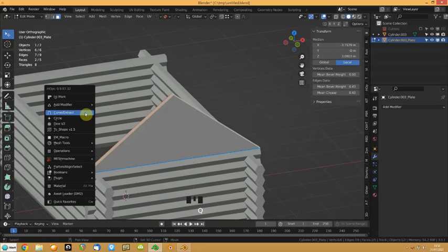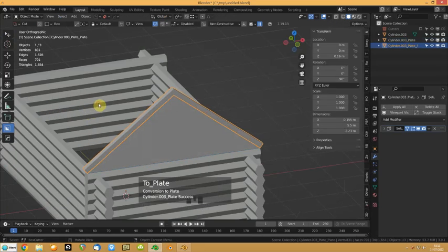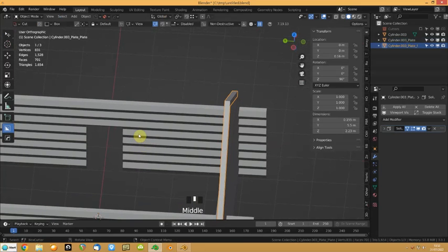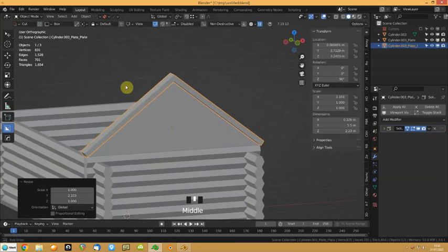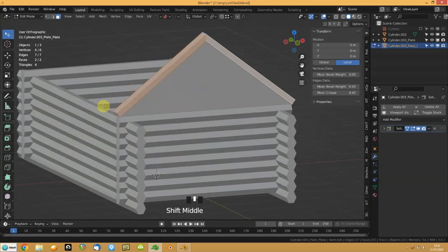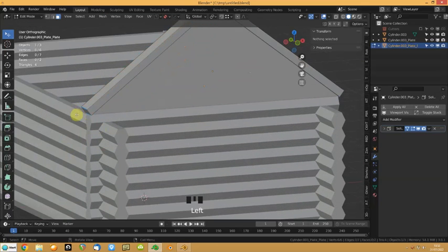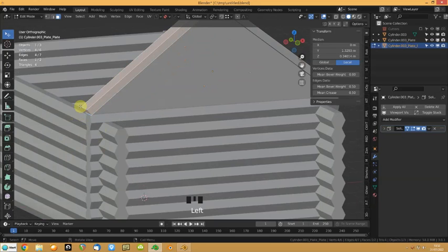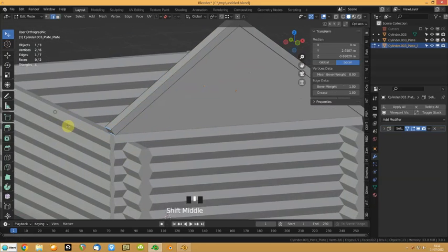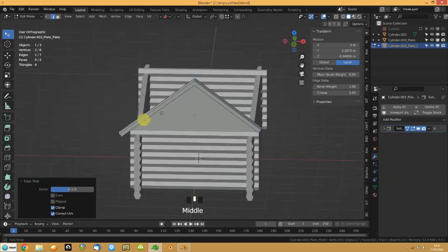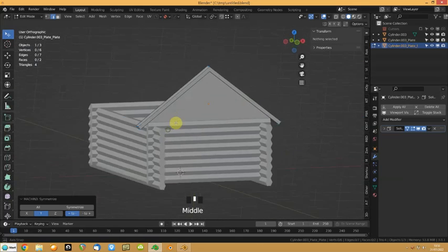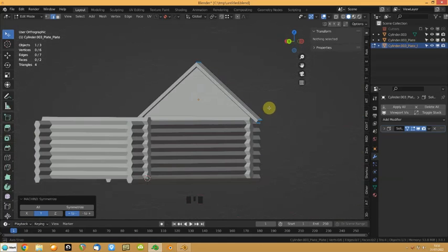And the same thing if you decide you want to then use this gable end to create a beam. I can do Q, shift click, go up like that. I can scale on the Y axis. Let's go into medium point, set the origin to geometry, scale on the Y like that. And I want an overhang. That's dead easy because we just select that. GG, C, like that. Alt X flip, guaranteeing it's there. And so there's your overhang.